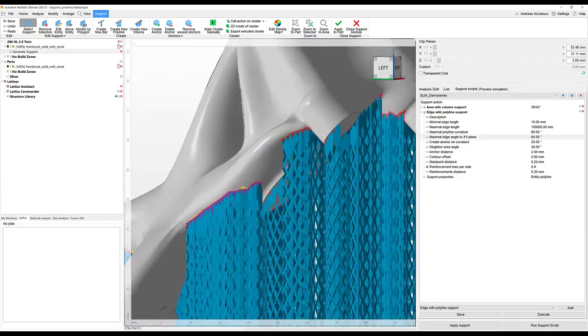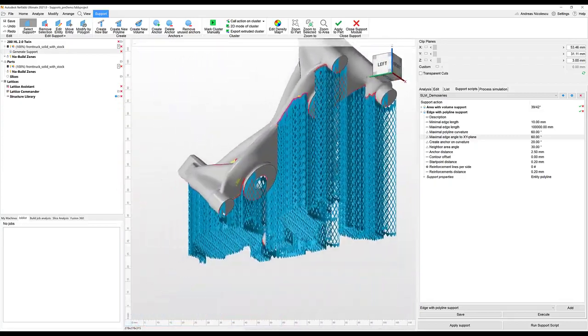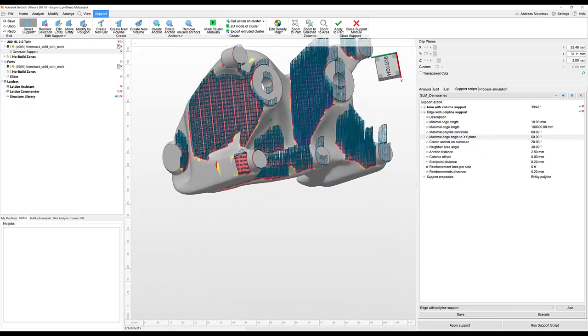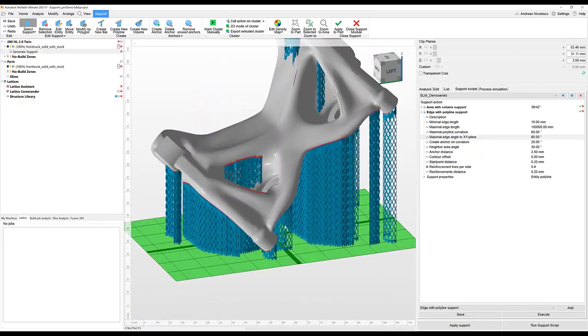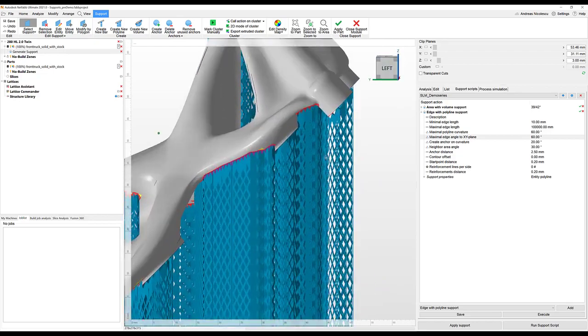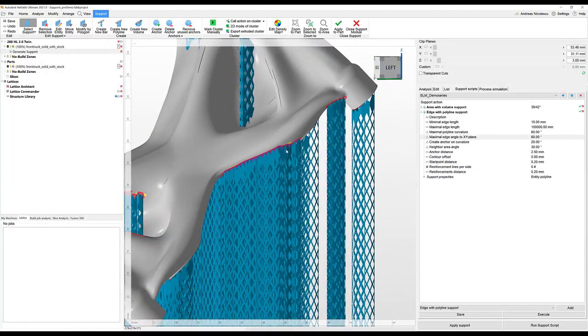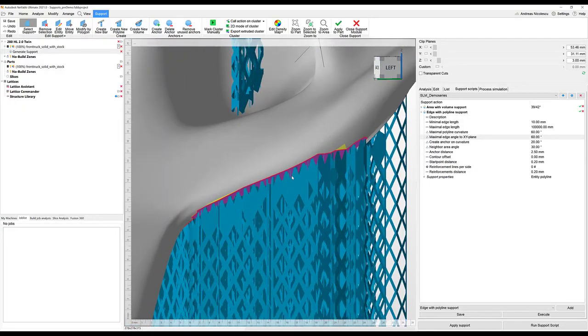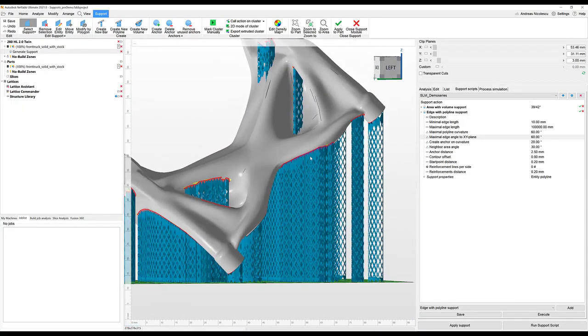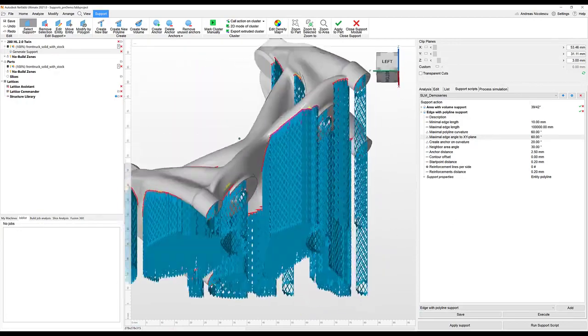Typically, when it comes to editing support, you can impact the detection mechanism, so the cluster angle, the cluster size, but you would also have support specific properties. Think about your block support, the size of the hatching, or in this case, how the polyline is going to look like. So all of these things can be edited within your support script.